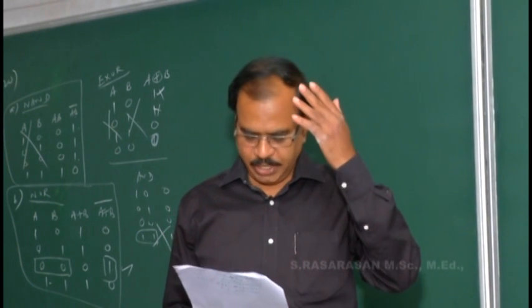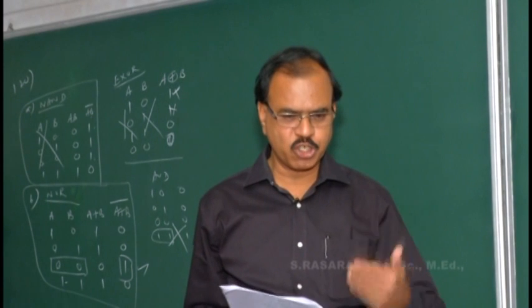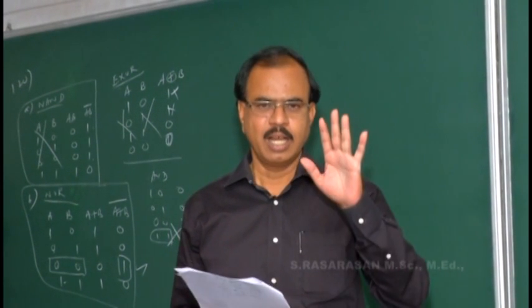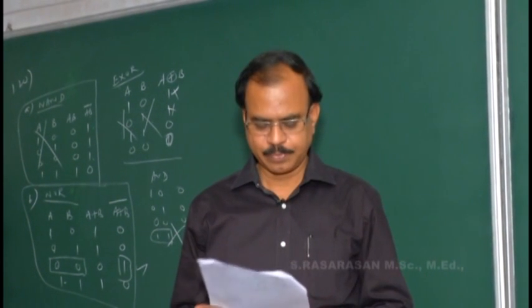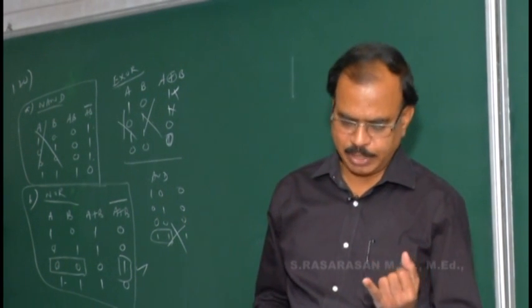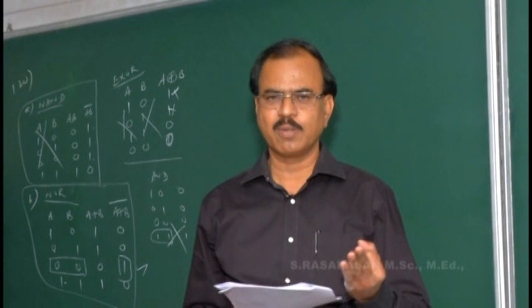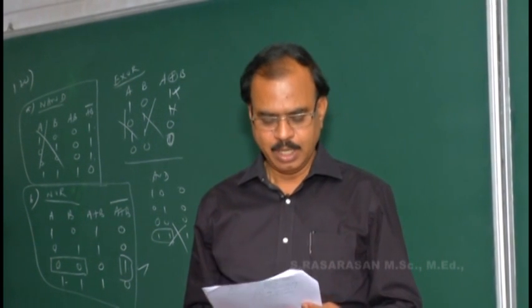So the video camera has a control grid, and the picture tube in our home also has a control grid. The thing to be given to that control grid is a high negative potential, and its name is the blanking pulse. So what is a blanking pulse? A high negative potential applied to the control grid to prevent the scanning when the spot returns from the right side to the left side of the picture or frame.